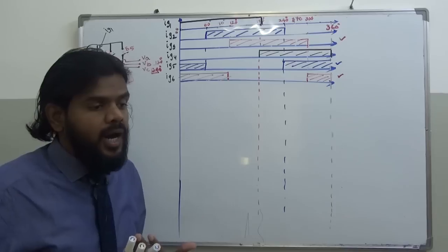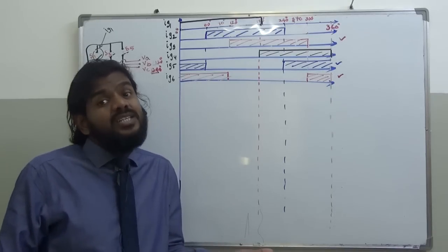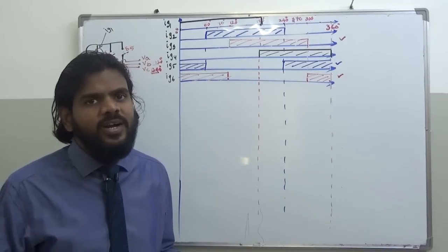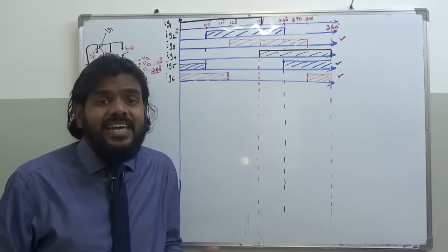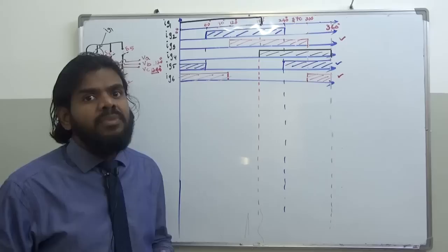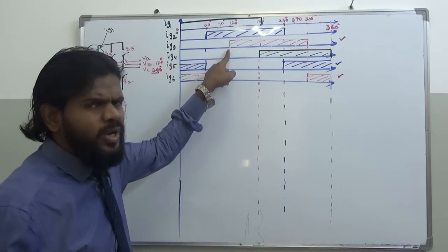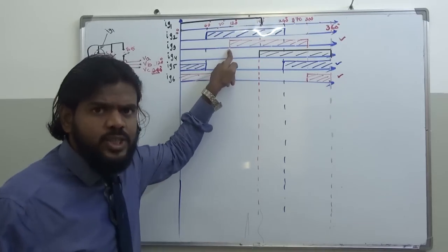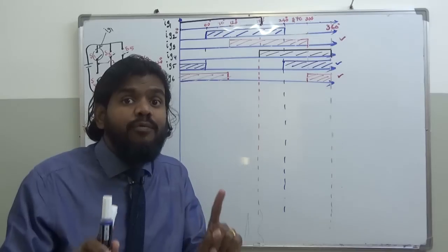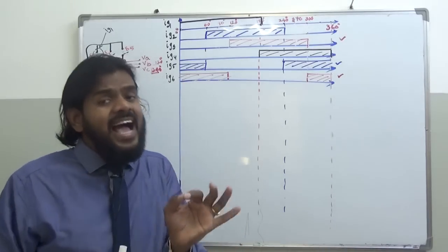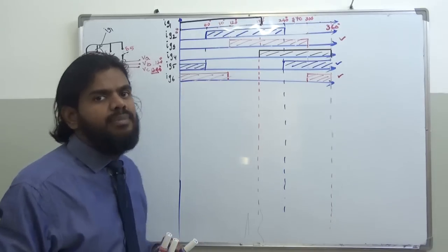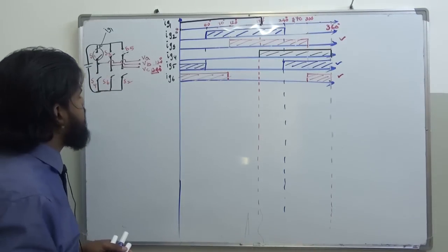It is about the output voltage, which is demanding us to turn on the switch 1 at 0 degrees and turn it off at 180 degrees. If phase B, because phase B is starting at 120, you got to make S3 on at 120. So it is not we to decide at which point the switch is to be turned on. It is the output required voltage, phase angles, which decides this instance at which we are applying the triggering pulses to the bases of all transistors.